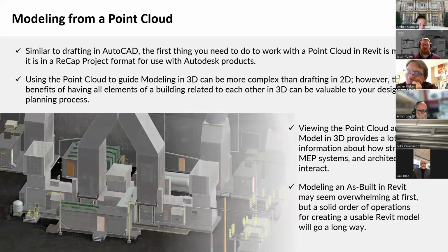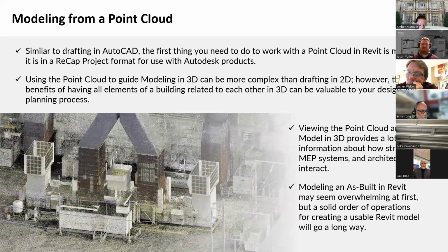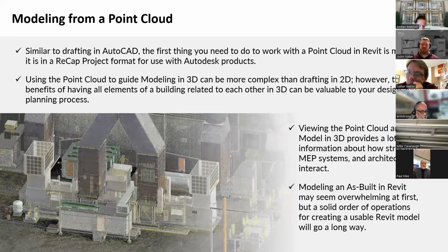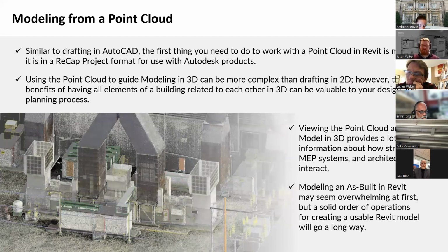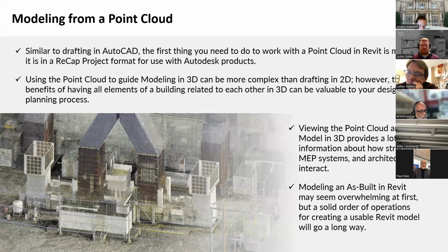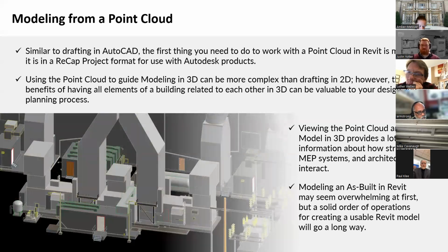Similar to drafting in AutoCAD, the first thing you need to do to work with a point cloud in Revit is make sure it is in a Recap project format, so you can use it with the other Autodesk products like Revit.